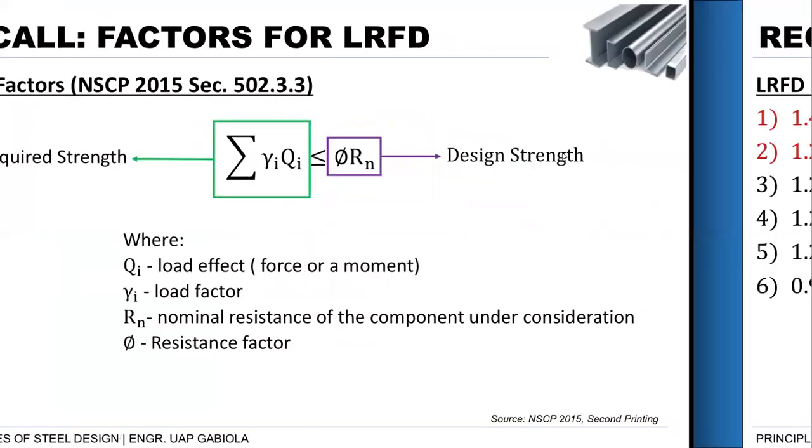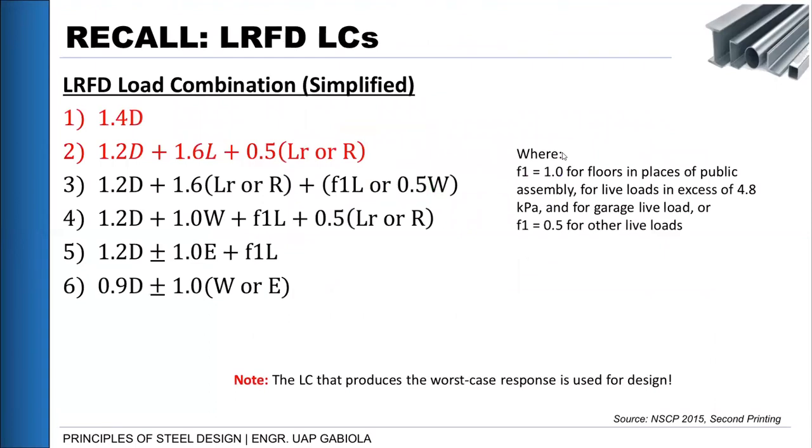Okay. And we also discussed already the load combination for LRFD. And as we have mentioned before, the load combination that produces the worst case response will be used for design. For problems where the givens are only dead load and live load, we will just focus on these two load combinations, which are highlighted on this sheet. So for dead load and live load givens, these two will be the only load combinations that we can actually check.